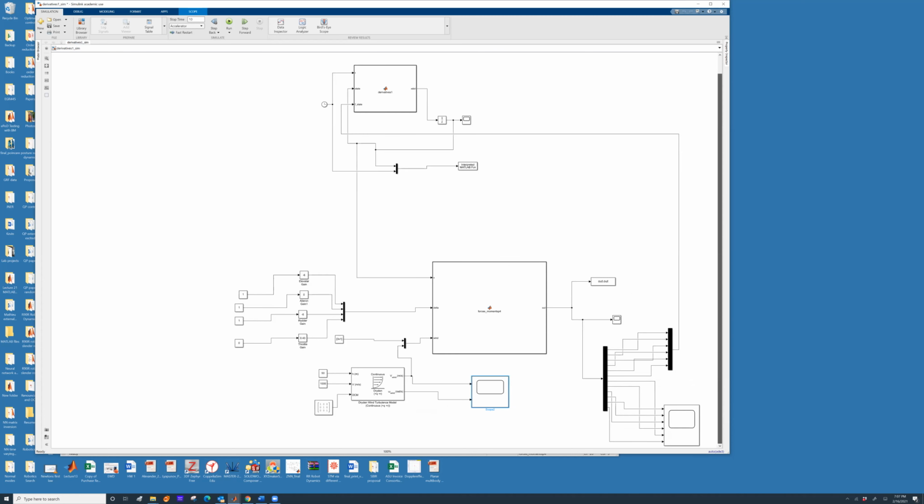So your airplane is Zagi. What you need to do is grab the output of this force moment. The output of force moment is actually 12 parameters. Look at the output of force moment. The first 6 parameters are nothing but the forces and the moments, and you have to be super careful. You should have force 1, force 2, force 3, Fx, Fy, Fz, and then you will have L, M, and N. Don't change this order for the multiplexer. Your results are going to be wrong.